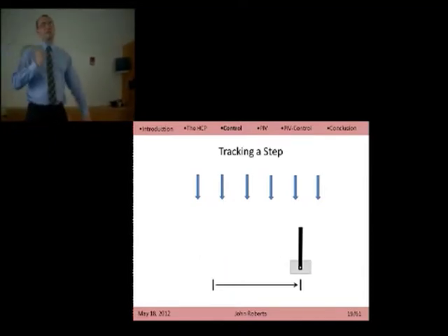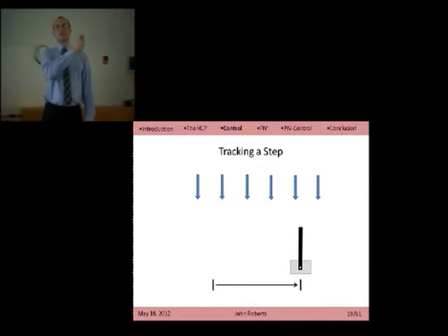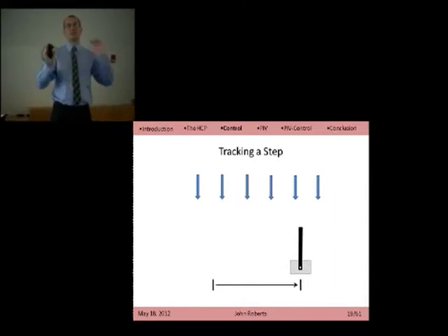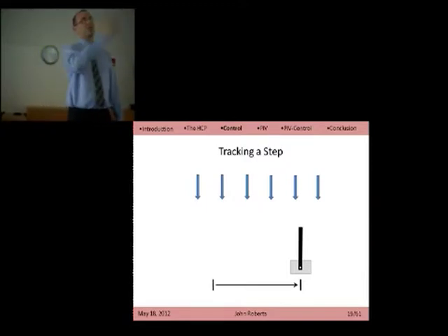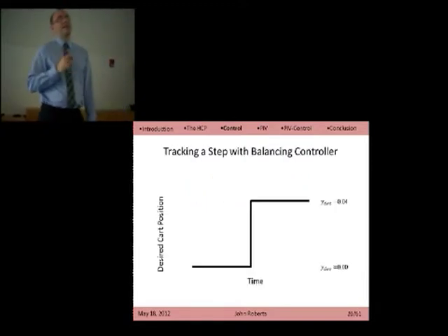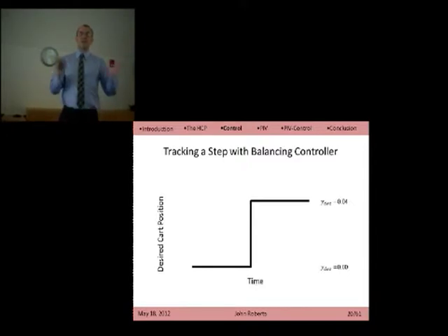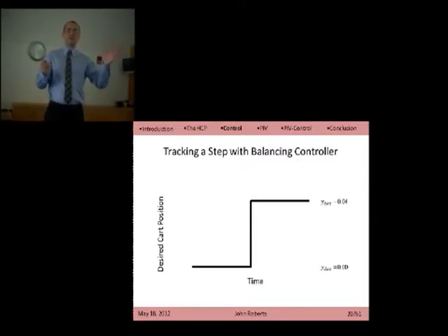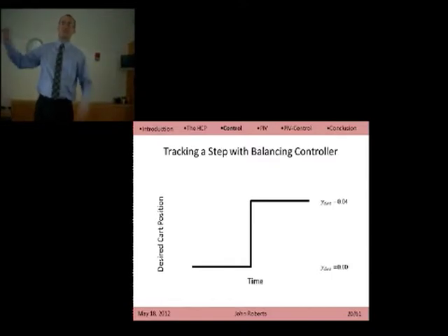And that's a characteristic of the underactuated system, and also in some way you can say this is non-minimum phase for some input-output relationship, and it's characteristic of that as well. So we want to execute that kind of maneuver. The simplest thing you could try to do is just use our balancing controller. So be bouncing around one point, and then suddenly tell it, oh wait, no, you're at the wrong state. You actually want to be 4 centimeters somewhere else. And it'll compensate for that the same way it would compensate for any other error.